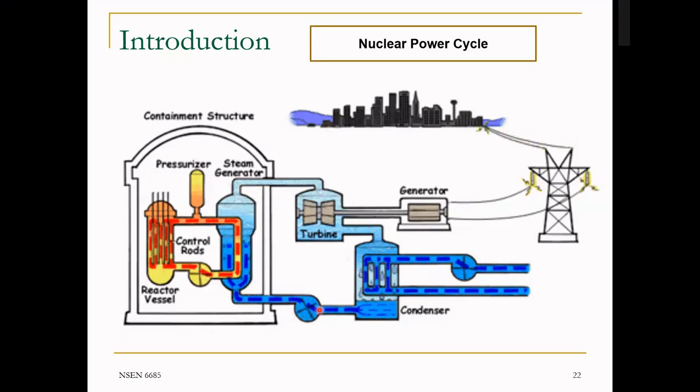Except we don't have a boiler or a steam generator to burn fossil fuel. So what we're going to do, we're going to have a secondary loop that's colored red here. That's a nuclear reactor where the nuclear fuel is sitting inside here. We have a nuclear fission reaction that produces thermal energy. Hot liquid is going to be circulated into the steam generator to produce steam. That steam will continue to drive the turbine, then condense back in the condenser. That feed water, maybe it's coming from a running river or it's coming from a cooling tower. Then it's pumped back to the steam generator.